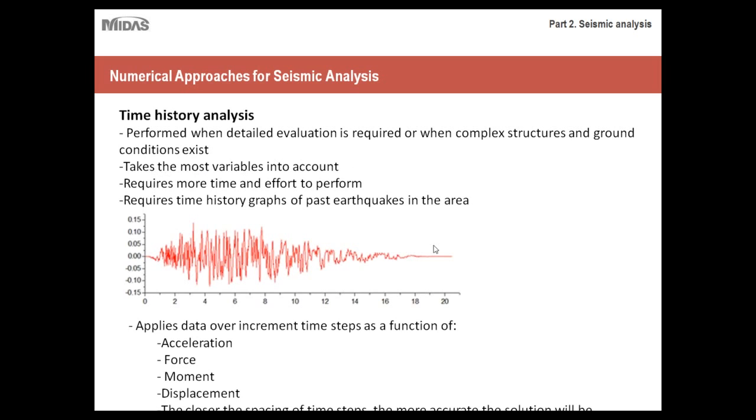As I discussed before, you'll need access to a number of time history records, and these are standardized. For those of you who work in high seismic regions, I'm sure you're well aware of the time history records that are available in your area. You need access to these records, and then you'd also have to import them into the calculation itself. I won't go into a very high level of detail, because time history analysis in and of itself could be its own lecture. But I just want to make you aware that time history analysis is especially useful for high loading or high seismic conditions.